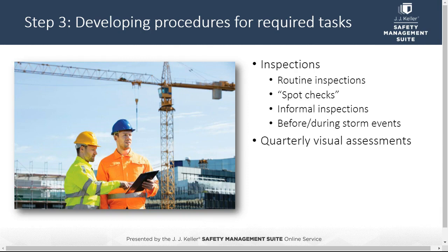Both general permits have requirements for a number of inspections. The inspection frequency typically ranges from once a month to once a quarter. No matter what the frequency is, EPA does recommend that you develop a routine inspection schedule customized for your facility and specific site conditions. In developing your inspection schedule, consider using spot inspections as a more frequent means to keep an eye on the higher risk areas and activities. So examples include construction site entrances and trash dumpster areas.